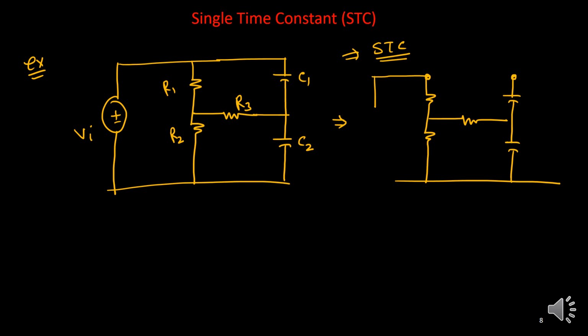So why not I consider two voltage sources instead of one voltage source? That I can do. This side again the same voltage source Vi in repeated way. It is called voltage source splitting concept. So this end is connected to a pure voltage source Vi, so I can consider this potential is Vi again, this potential also Vi again.